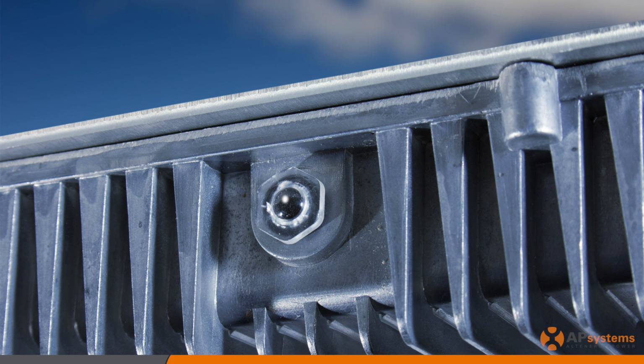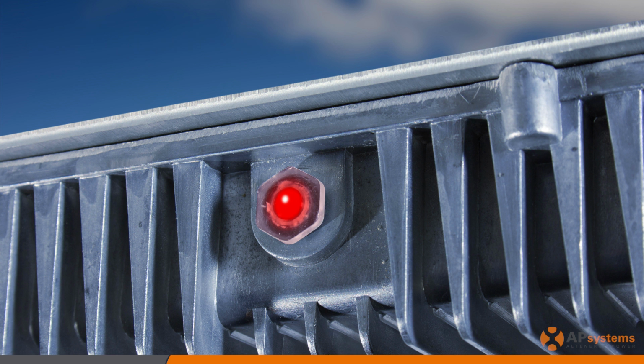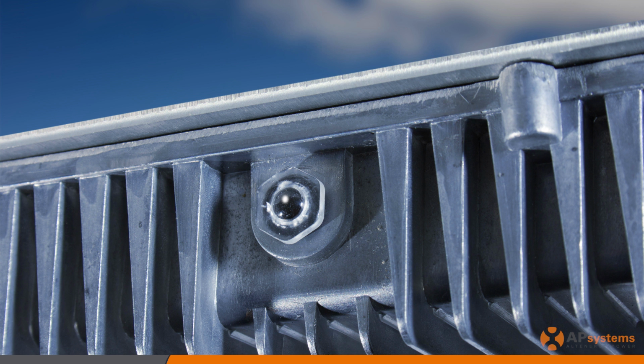Now that the system's energized, a few words about the inverter's LED indicator lights. The inverters have an LED indicator that is extremely useful in determining the system status beyond system startup. Assuming all is good with the system once it has been energized, the LED will flash green slowly every 10 seconds, meaning the inverter is producing power and communicating with the ECU as expected.